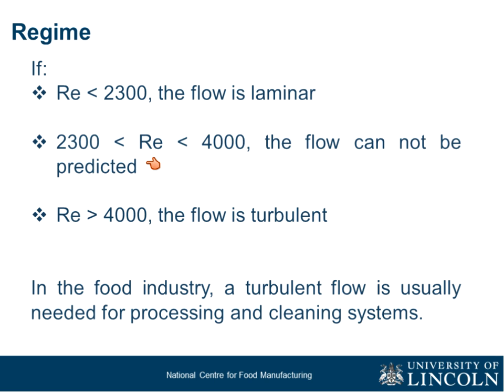We'll talk about when this is very important. If you are doing a cleaning operation, cleaning in place in your equipment, you want the flow to be turbulent because you want a rigorous contact, a rigorous mixture between the cleaning fluid, the cleaning agent, and what you are trying to clean. We want that to be rigorous. So you want that flow to be turbulent.